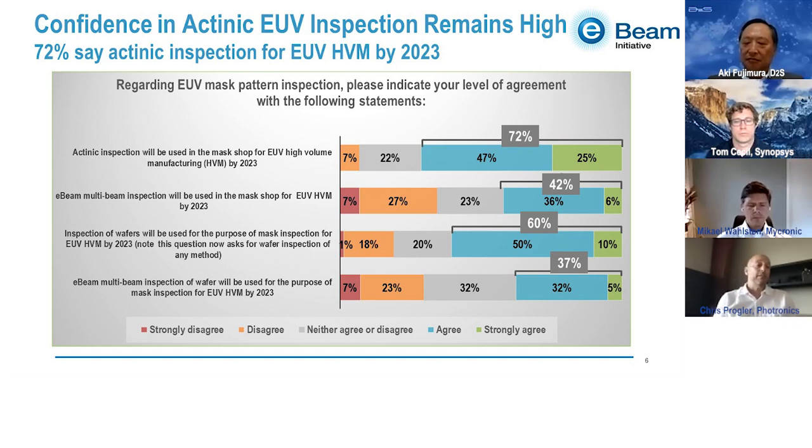As far as the E-beam, the second piece, the mask maker using a high-speed E-beam system, it would be very nice to have both. This is an affordability question, but if we had to pick one, we would use 193 and EUV actinic for the primary inspection capability inside the mask operation. The one thing nice about high-speed E-beam systems is a multi-beam SEM. Actually, I would almost prefer to see that deployed on the CD metrology side more than straight inspection, because CD metrology is a big challenge.